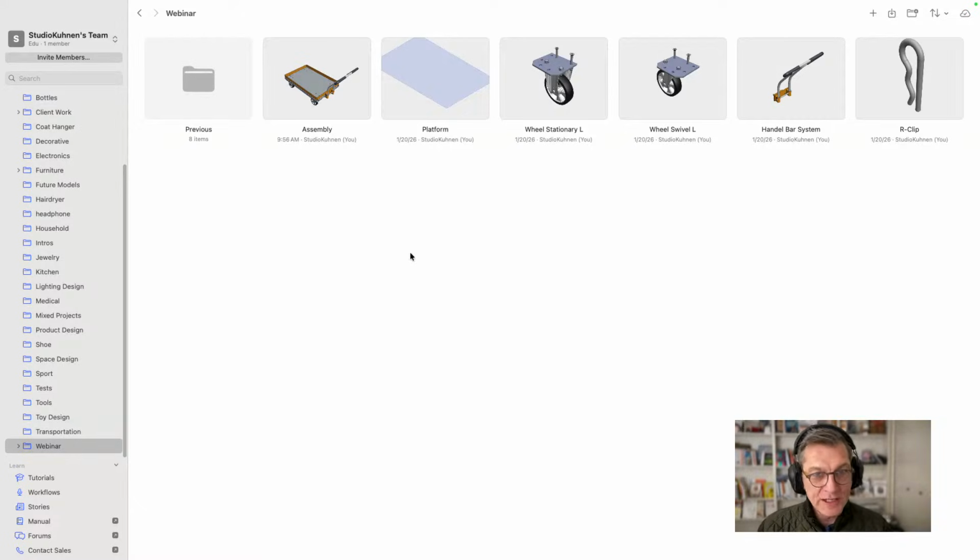So today's topic, as Danielle mentioned, is variables. They are really very useful. Think about this as dimensions you can globally define, and then you can use variables in sketches and modeling features. So that means you can drive multiple design steps just by controlling that via one variable.